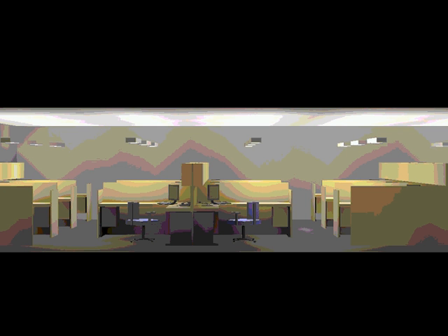And this is an example, a picture of maybe what the space would look like. Direct indirect luminaire is going to light the ceiling, which is going to bounce light onto the walls. We've got high reflectance surfaces on the partitions. Again, we don't want to get a cave. We don't want to get cave low down. We've also reduced the height.